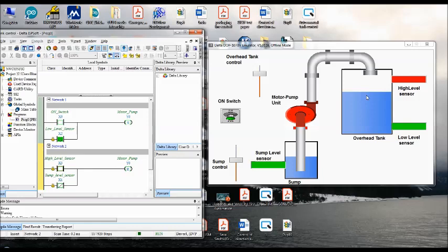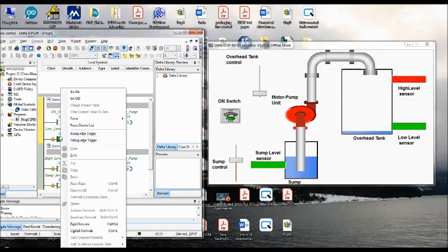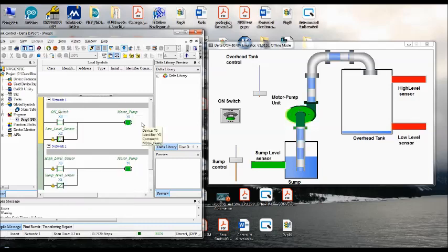Now the water level is reducing, reducing, reducing, and the water level is really lower than the low level sensor. Then the low level sensor goes off. So this is the application of falling edge detection. Off, then automatically the motor is on. I hope you understood. So we are assuming constantly that some sensor is on, that means enough water in the sump.